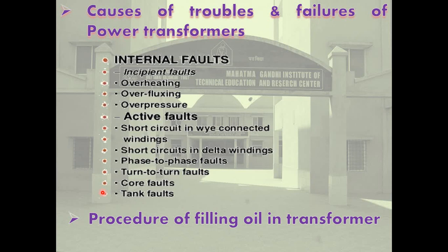Next is various steps in commissioning of the power transformers. There are pre-commissioning checks on the transformer, tap changer, bushings, protection systems, control systems, marshalling kiosks, main connections, control connections, cooling systems. Then there are commissioning tests, polarity check and phasing, energizing and operation under observation, loading and observations. Okay, most important steps in commissioning of power transformers.